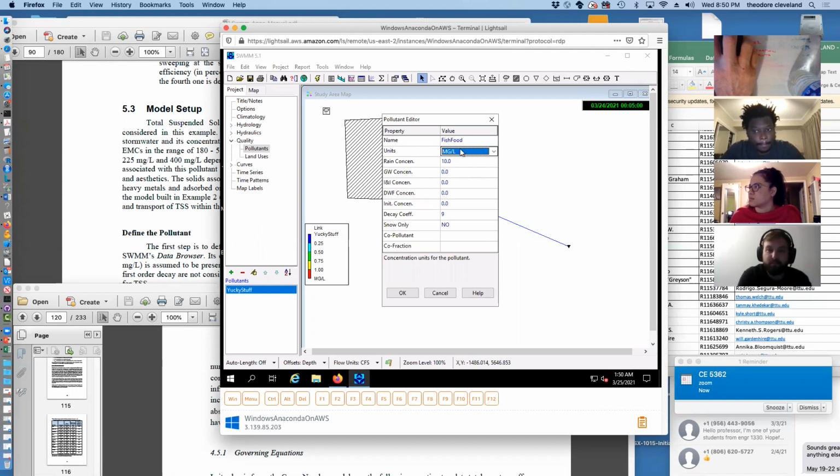And the units are always mass densities. So milligrams per liter, micrograms per liter, I guess that's pounds per liter, a mass density. So the units will make all my environmental engineering colleagues very angry. The units are essentially dimensionless. They only represent a ratio to a volume, and you have to use external calculations like area and flow rate to determine that volume to recover actual masses.